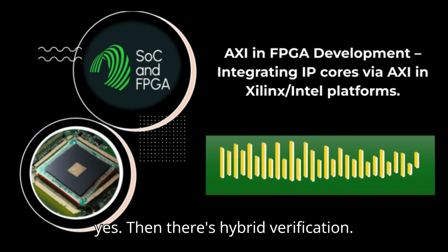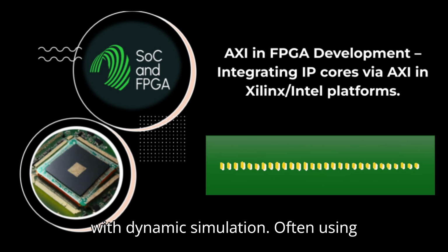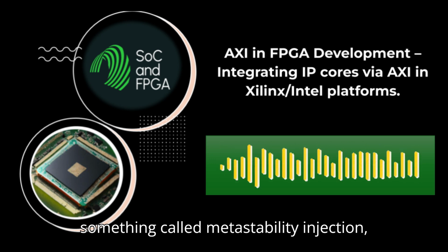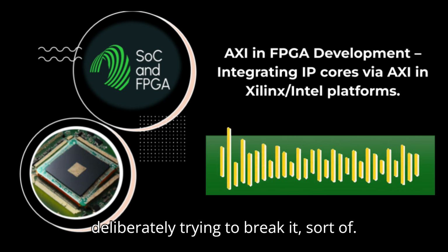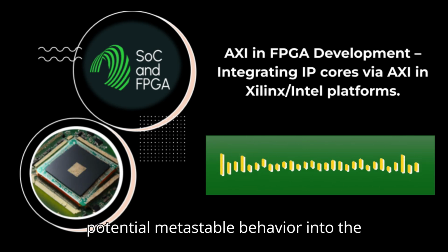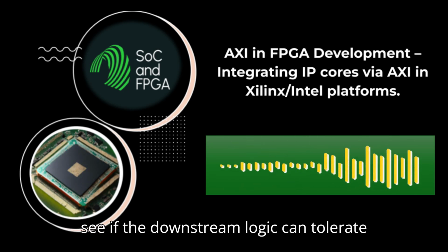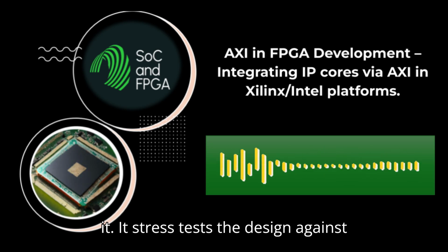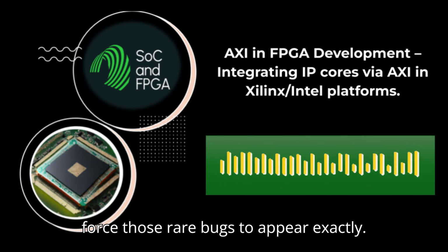Typically, yes. Then there's hybrid verification. This cleverly combines static analysis with dynamic simulation, often using something called metastability injection, or MSI. Injecting metastability, you're deliberately trying to break it. Sort of. You inject timing uncertainty or potential metastable behavior into the simulation model at the CDC boundaries to see if the downstream logic can tolerate it. It stress tests the design against real-world timing variations. Trying to force those rare bugs to appear.